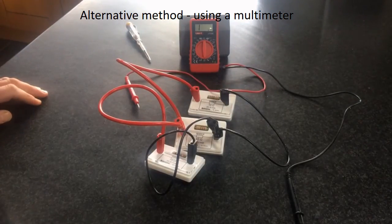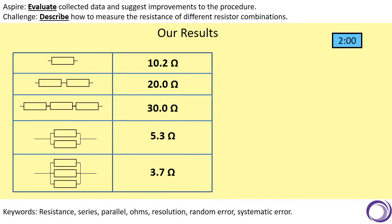3.7 ohms. Here's the results then that I've popped into this table. I've just done it with a diagram, so you can see on the second one down we've got 2 resistors in series, and that gives us 20 ohms, and each resistor, if you remember, was 10.2 ohms.